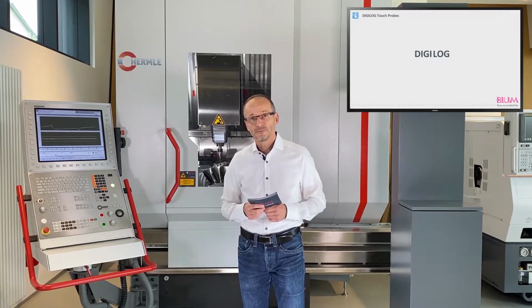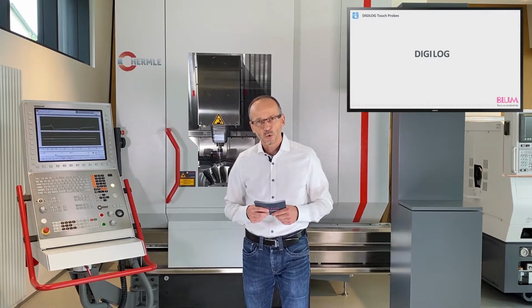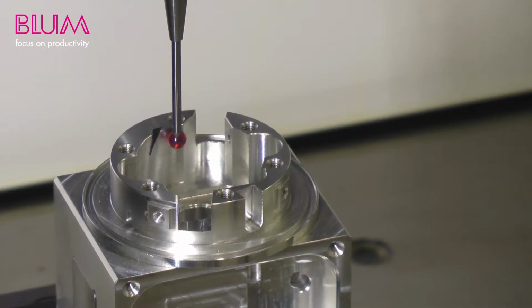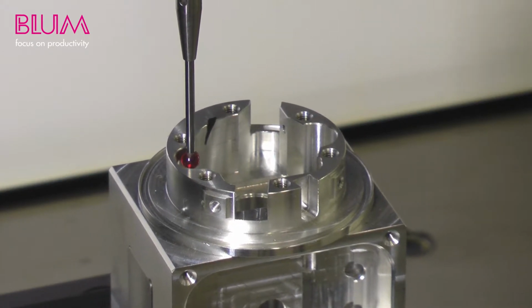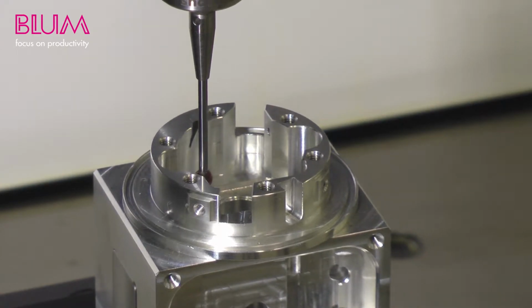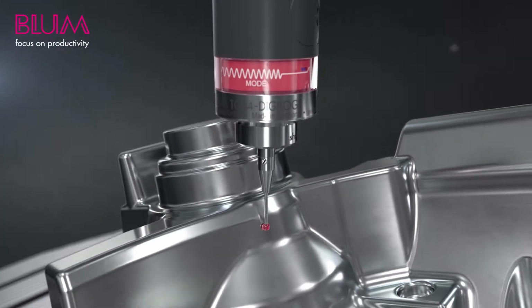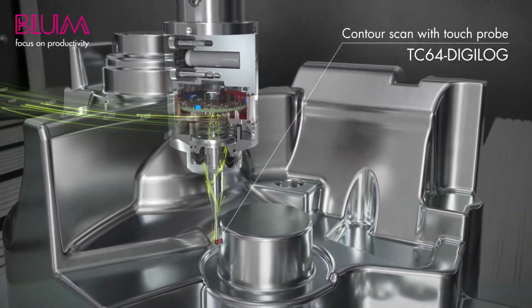Analog means we not only recognize whether the probe is deflected or not, but also recognize how much the probe is deflected. So we actually monitor the degree of deflection. At the same time, we don't just generate a single signal during the measuring process, but instead we record a large number of measuring points during the entire measuring process. We're basically generating a data stream. A data stream in which thousands and thousands of measurement points are generated and can be used for evaluation.